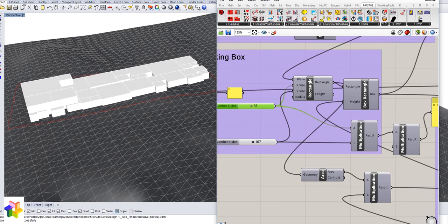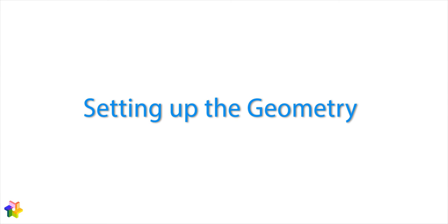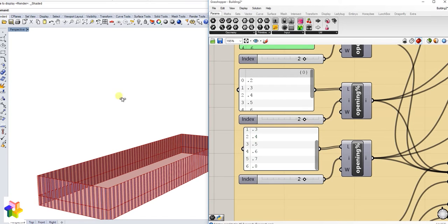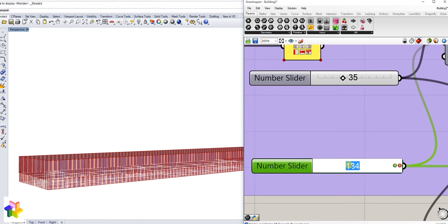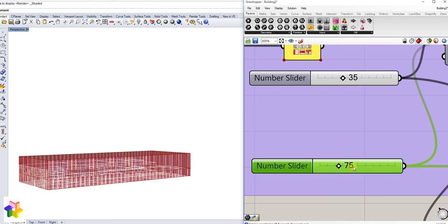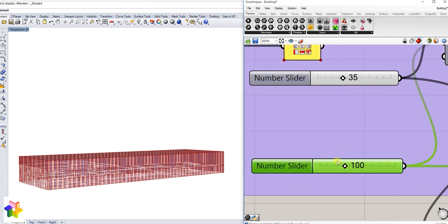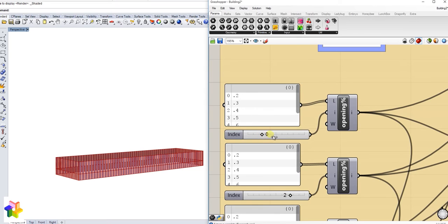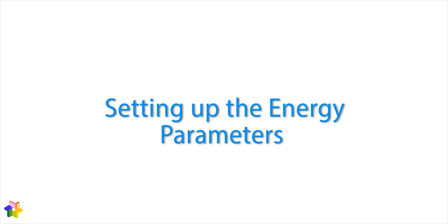And once we define the overall basic massing that works with the program, we start looking at the overall shape for the massing. What does the shape need to be to meet our set performance targets? We set up varying glazing percentages for each of the facades, 30%, 40%, 90%. How do we find the balance between a low EUI and high daylight factor?